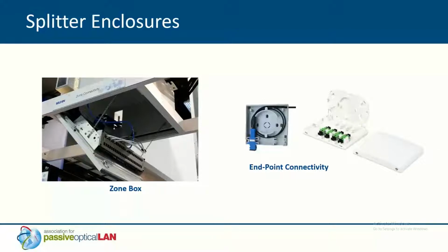So if you're going to put these devices and zip tie them to the structure up in the ceiling, you have to consider the connectivity. They have a plenum rating, which is UL 2043, just like we have to have that rating on our cable, which is CMP.